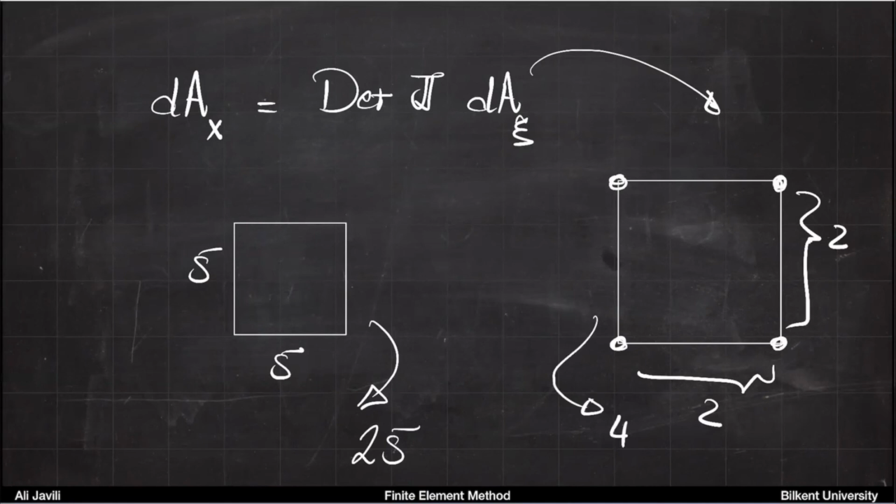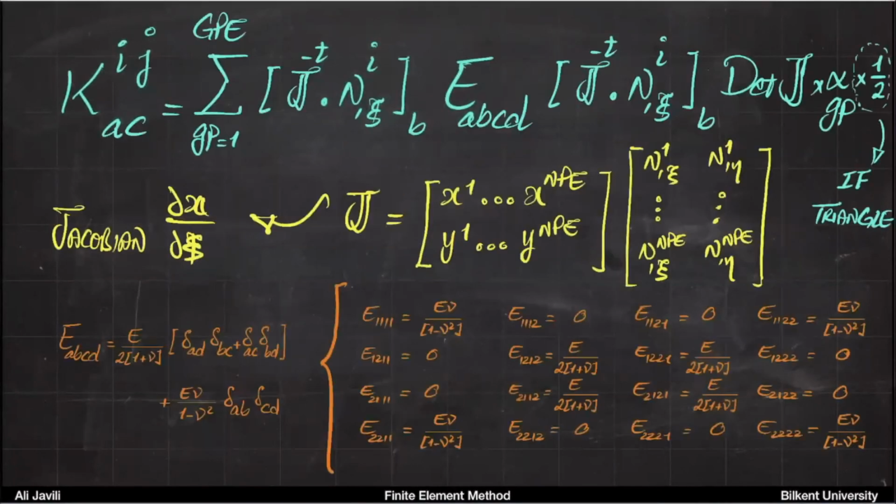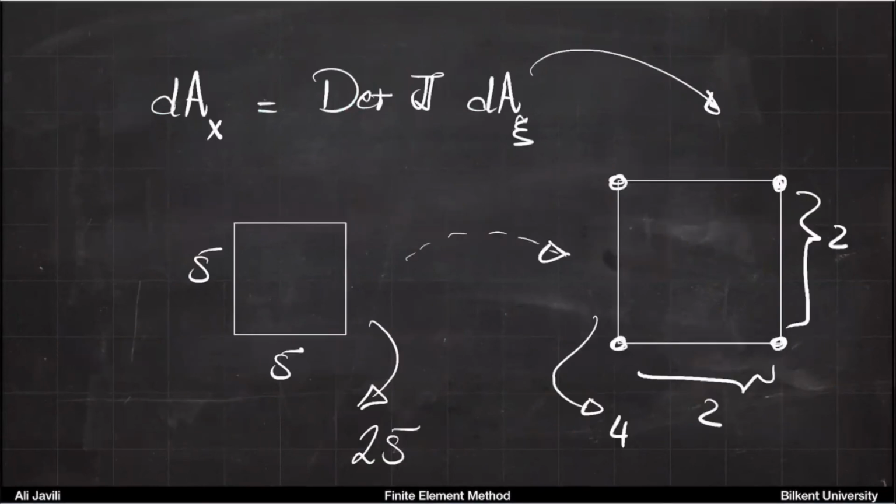When you construct that mapping using exactly what we had here, see, we have everything. You have your shape functions for that. You have the coordinates. You can calculate J, right? You just get that matrix. You construct that matrix, you calculate the determinant of that matrix, and you will get 25/4 for that determinant. Okay, so this is going to happen basically. In this case, your determinant here would be 25/4. Does that make sense?